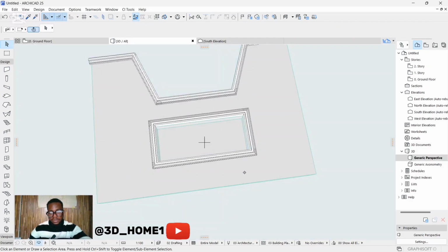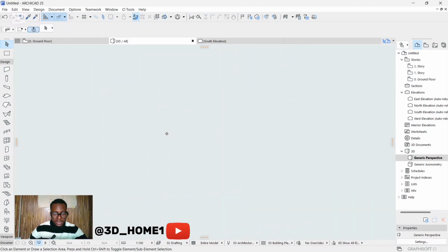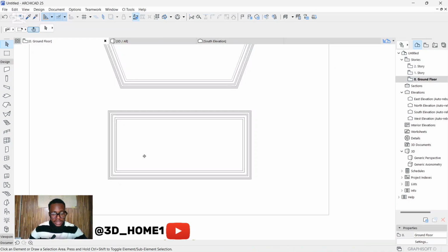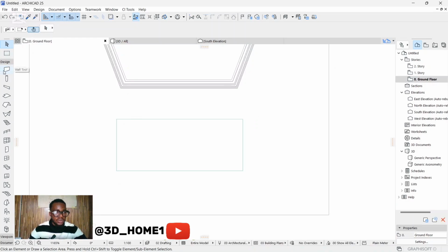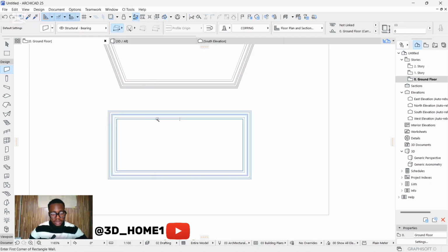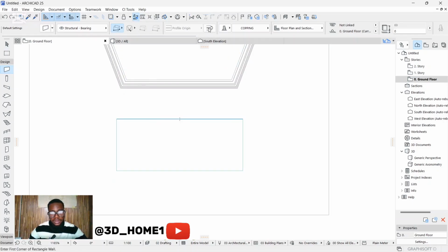You see that you have that same design here, but this time around this one is up. So what will happen is we need the design to be inside, not outside. So once you click on wall, let's say instead of out into in, let's select this.